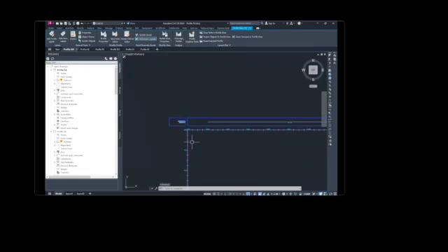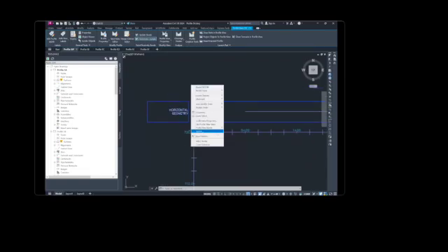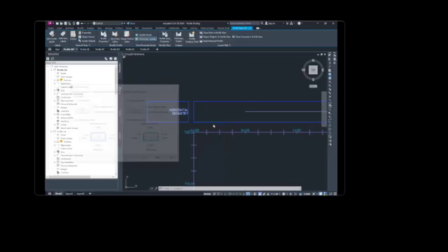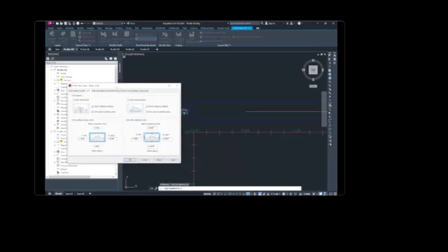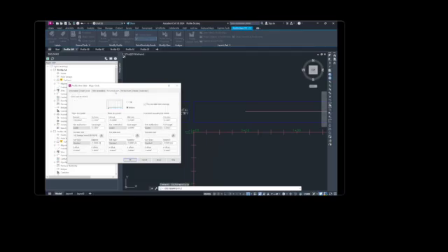In the next step, you will correct the overlap and modify the justification of the ticks and the major stations. So click the grid, right click, click edit profile view style. In the box, horizontal axis tab, click top. Under major tick details, specify the following parameters: tick size 0.25, Y offset 0.1. Click apply.